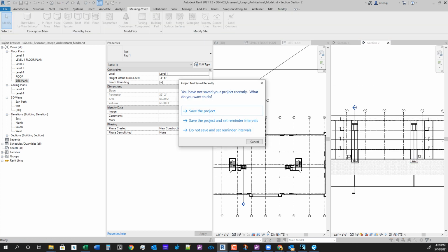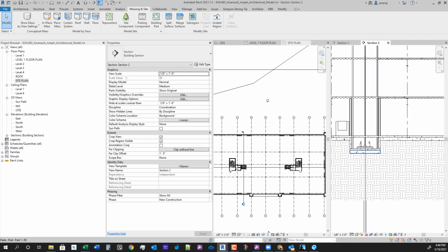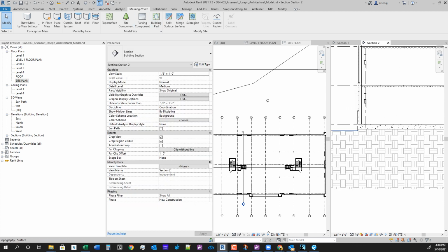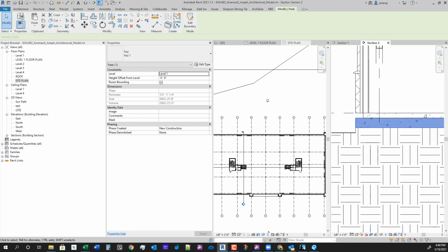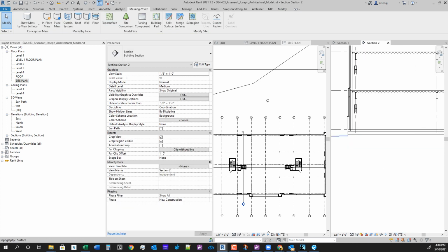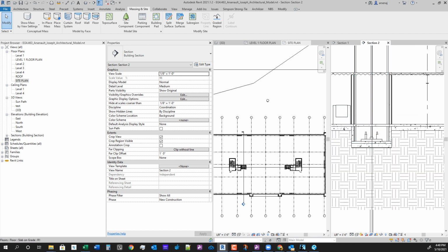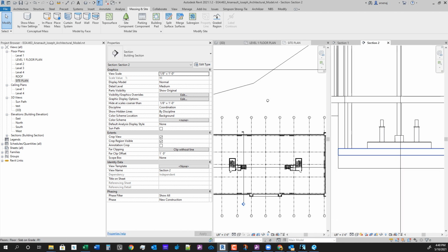And then, just a quick recap of what I just did. When I draw these building pads, we will go to the site plan, and it causes it to raise or lower the building grade to be with the bottom of the pad. So I did that so that the grade would be up here next to the building, but where I have my elevator pit, I don't want all this earth hatch pattern to be inside this elevator pit.